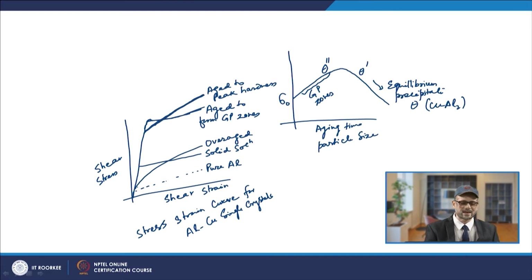So the yield strength is low, but the strain hardening rate is very high, and the dislocations accumulate in tangles around the particles in the process of passing between them. In that case they promote slip on secondary slip systems.